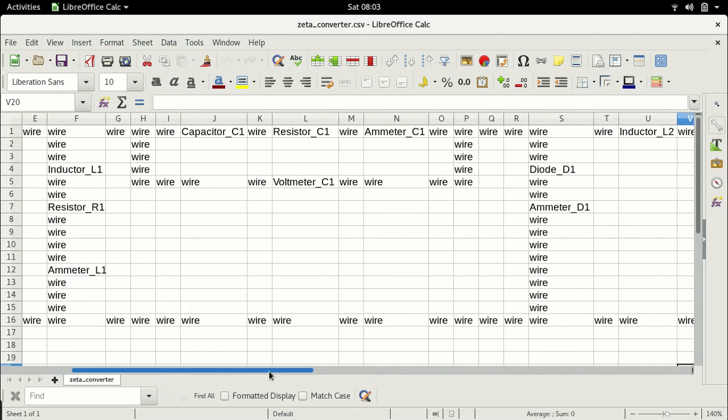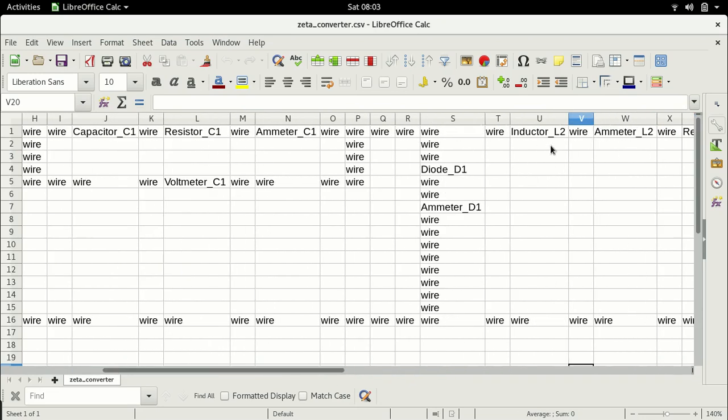Now, as the current starts flowing through, initially that's how it is, because you know the principle of an inductor, it will not allow the current through it to change instantaneously, which means as the current is zero, it will block the entire voltage and the current will gradually start increasing, right?